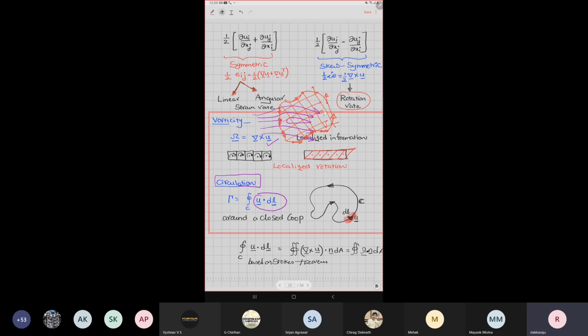Let me put it once again. You might take an aerofoil and want to understand what is happening with the flow features. I don't have to construct measurements throughout the aerofoil. What I can always do is, this is my aerofoil, I can put some probes here, 1, 2, 3, maybe 4, 5, 6, 7. These points are good enough for me to get information on the velocity field, because I keep probes around these aerofoils, which are kept in wind tunnels, to understand the lift and drag force acting on them, and so on.